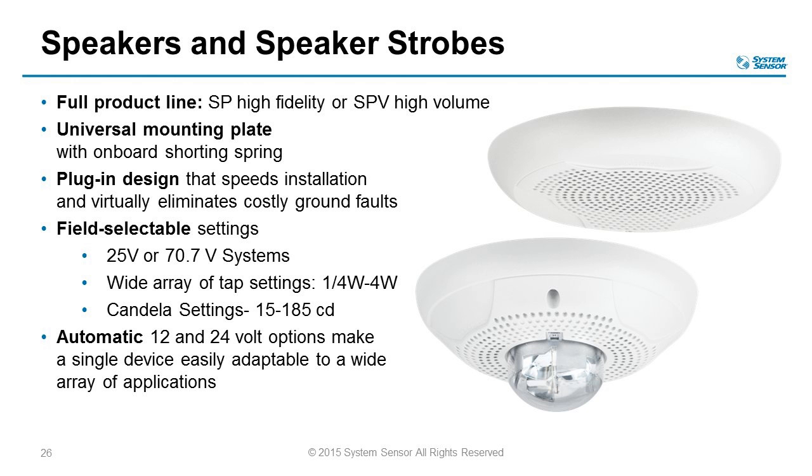These devices use a universal mounting plate with an onboard shorting spring, which ensures wiring continuity before the devices are ever installed. So the installers can verify that you have your proper wiring without actually having to mount the device, and prevent damage during construction.